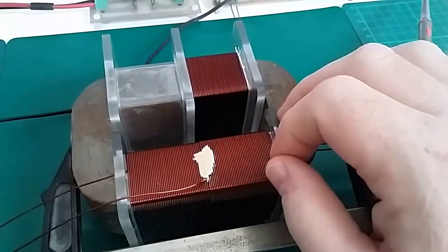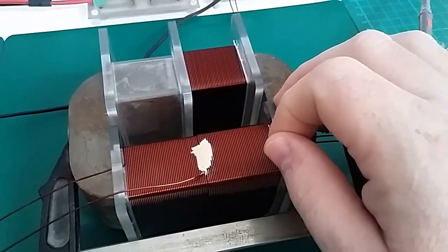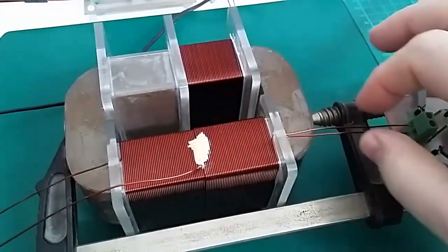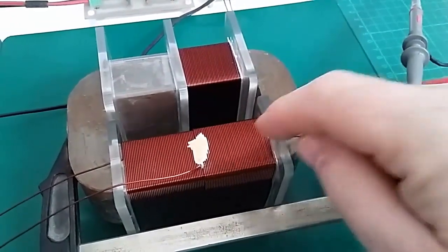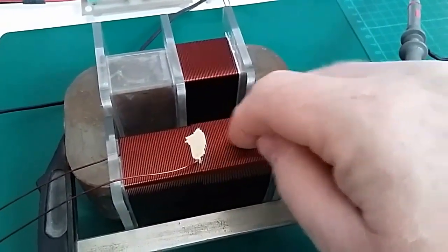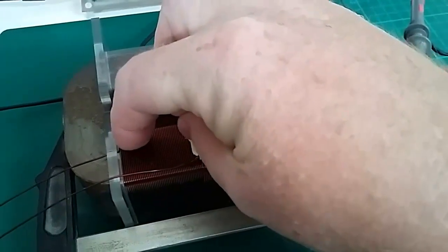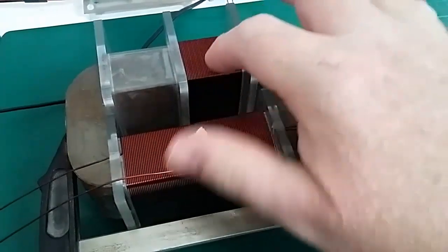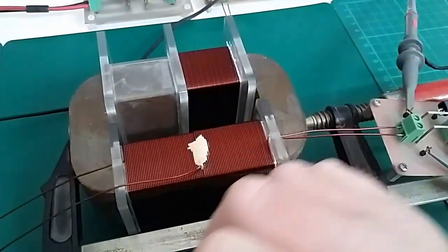So there are various different ways to do it. At this stage of this experiment, I will do a few more things and then we'll make steps ahead. But at this stage, what I have shown is the direction of the current in the coils, where this part here is non-inductive, which gives us a different coupling coefficient, a different coupling between here and here. And we'll do some math on that in a minute.